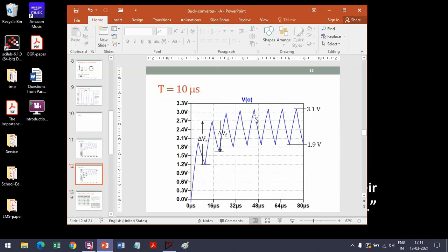Alright, if you are interested, you can sit and go through the mathematics of these cycles one after the other, and mathematically you can convince yourself that this happens independent of the value of R, the value of L, the value of the input voltage, the value of capital T. It doesn't matter whatever values one uses, it is a property that eventually such a system will settle down to oscillating between two constant voltages.